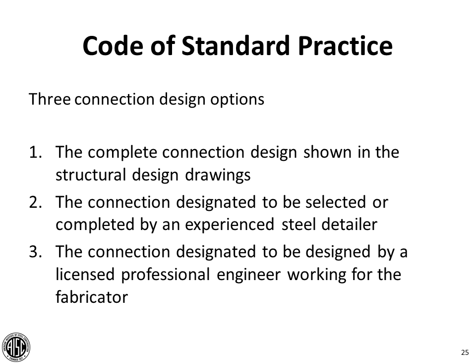I'm going to be talking a little bit about some differences between different connection design methods that can be used or can be designated on projects. And so I'm going to give a little bit of an overview here of what's possible. So there's three options given in the Code of Standard Practice. All of these could be applied to both seismic and non-seismic projects. Options 2 and 3 are probably a little rarer on seismic projects.